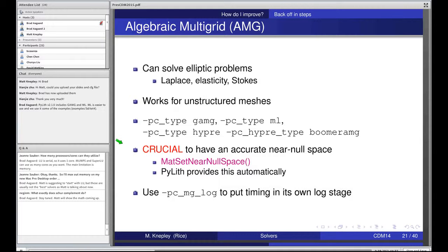So in that sense, you have a null space corresponding to translation in the up and down direction. That will cause either a singularity in your problem or ill conditioning, and your preconditioner will stop working. So understanding these null spaces is worth it when you set up the problem, because they can explain when things go wrong.